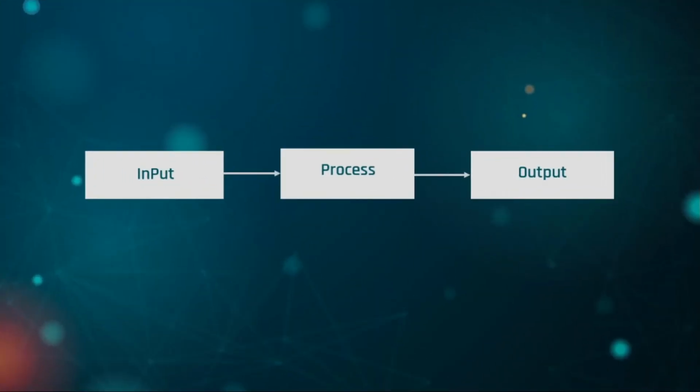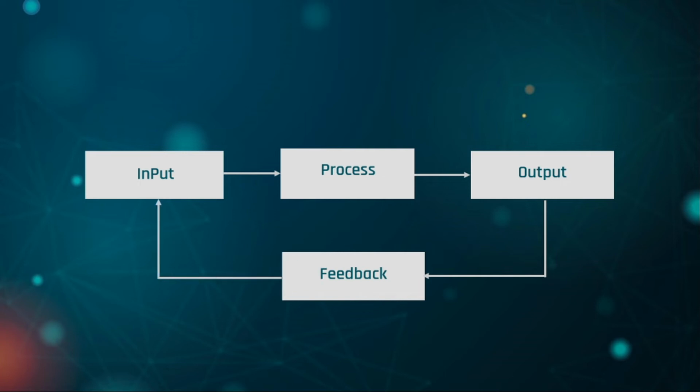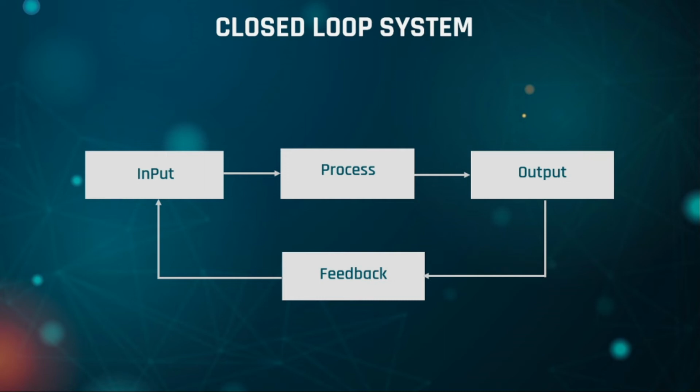Now what is a closed loop system? When my output is sensed again, to see what kind of output has been generated, and that output is given as feedback to my input along with my input to my processor, my processor now compares the actual input as well as my output. Until my output matches what I prefer or what we desire, my processor performs to maintain that standard output. So this is a closed loop system.